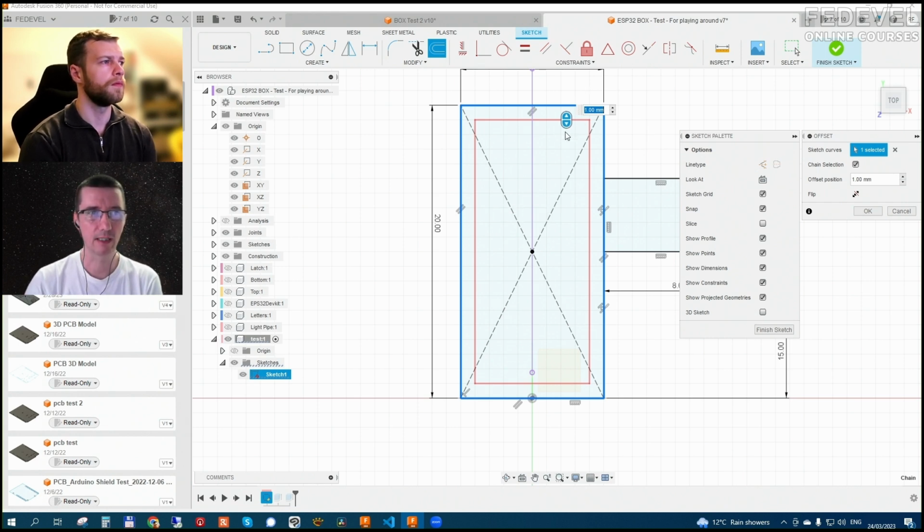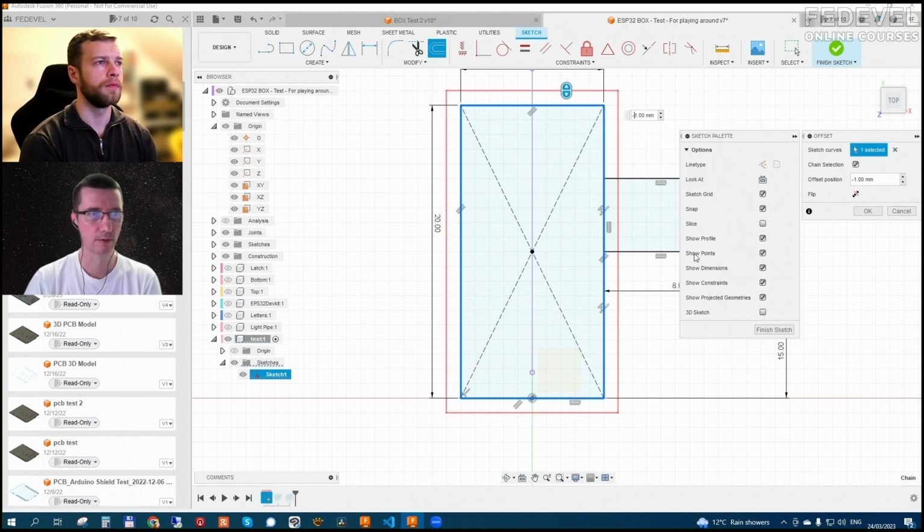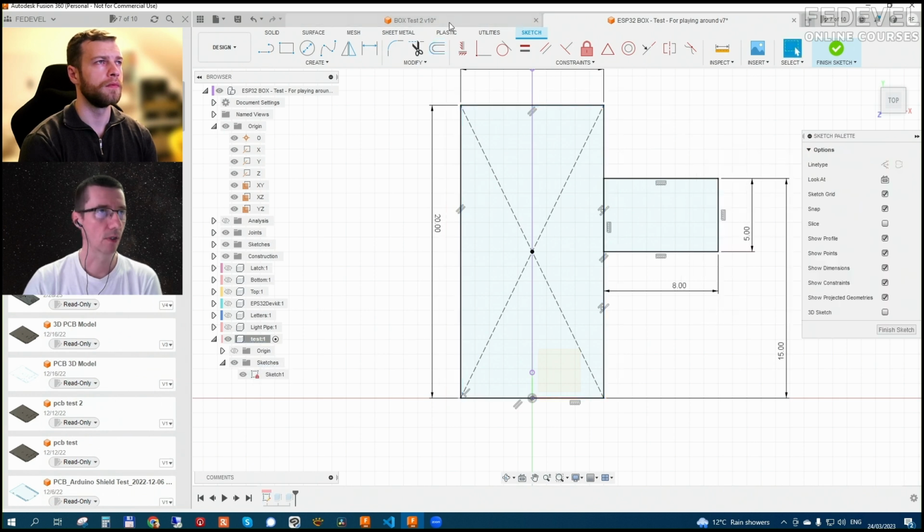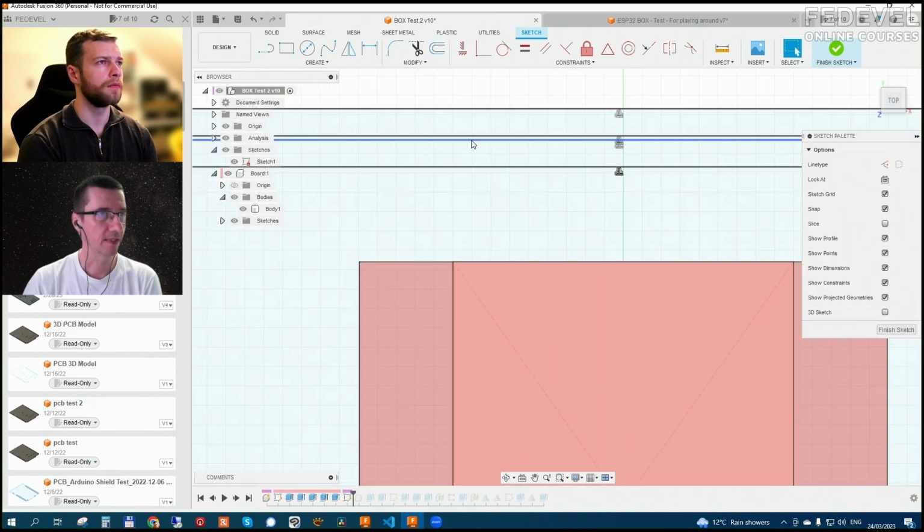I use it very often because you can very easily go around the object. You don't have to redraw it manually. You just specify 1, or you can put here -1 and it will go around. Okay, so all this, what you can see here, this one and this one, these are all created by offset.